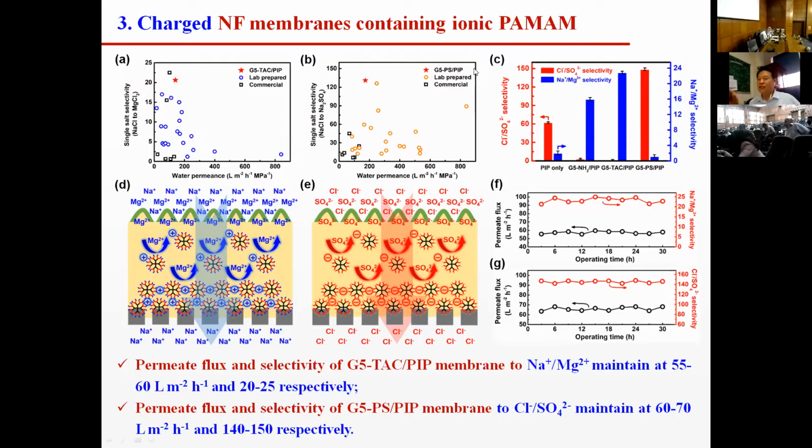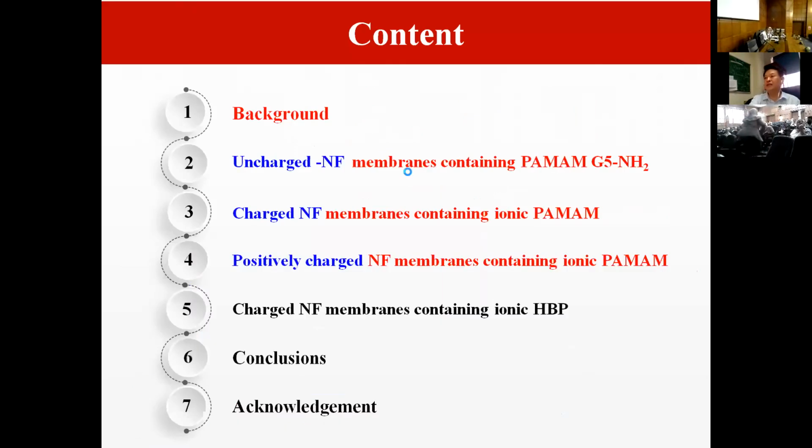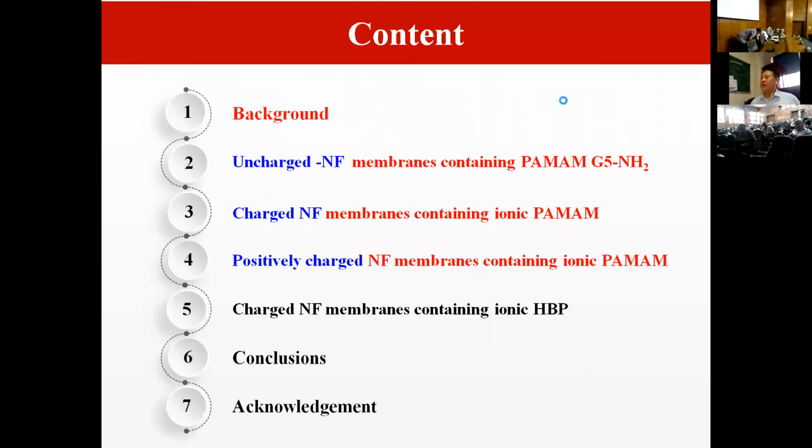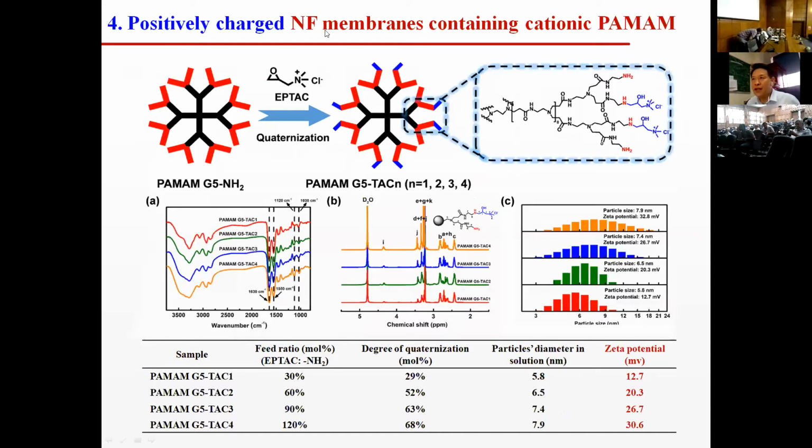The separation factor is very high compared with the other reports. This suggests that the charged nanofiltration membrane can be effectively prepared by the PAMAM-based dendrimer. However, we select the positively charged nanofiltration membrane and investigate the salt separation property in detail.